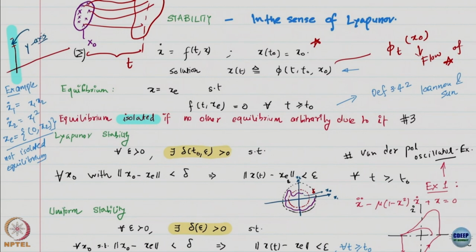So, how do you compute the equilibrium? You compute it by equating the right hand side to 0, because that is what makes sure that x dot is 0. If x dot is 0, states are not moving anywhere. So, you are fixed in state space, and that is essentially what you want, you are at equilibrium. So, equilibrium is computed by equating this to 0.